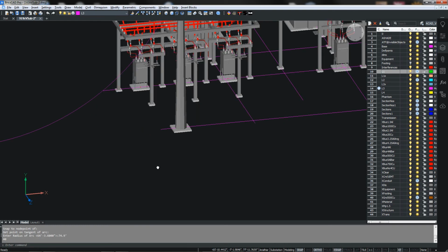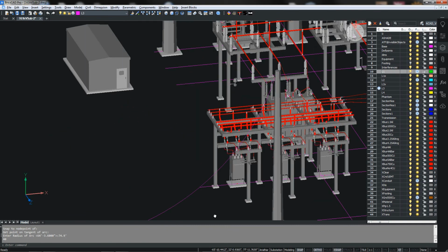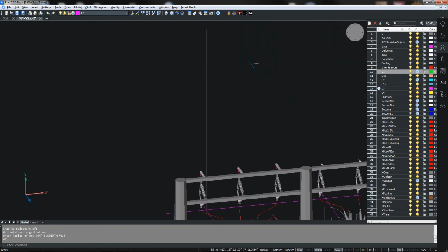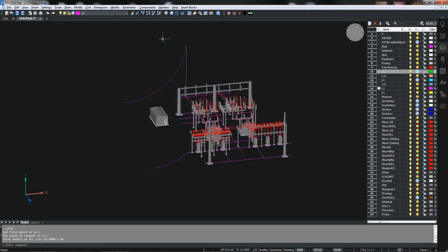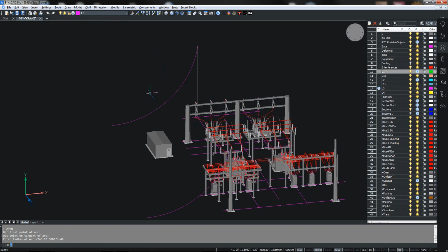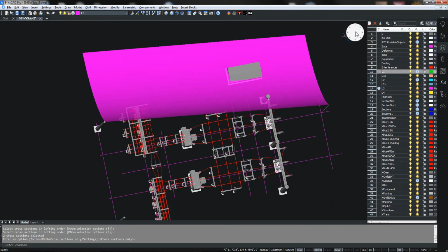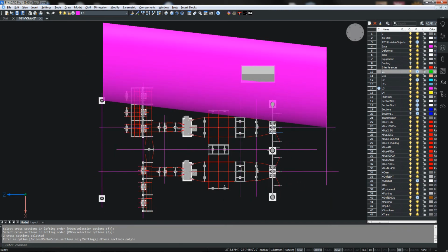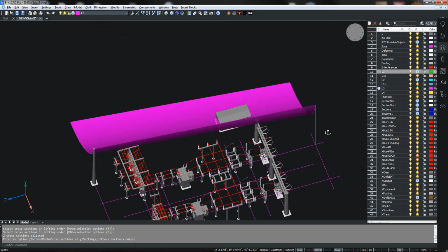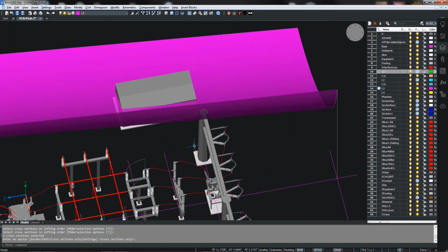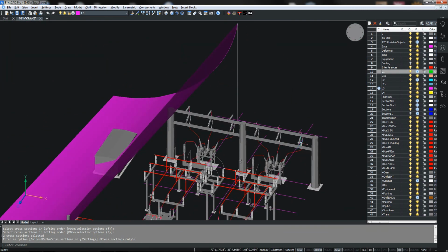So there is our arc for the 74.9 feet for the 161. We'll come back here and again use our APTR and 74.9, and then we will loft these two. Loft the last one and this one, and then if we look from on high, we are well over the top of our 161 switch with that one. I don't think we need to go any further with that. It's just the same thing over here.